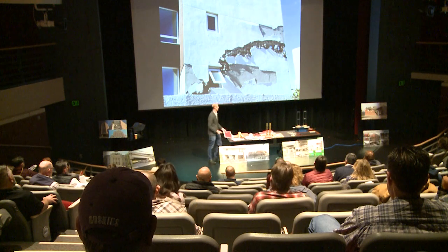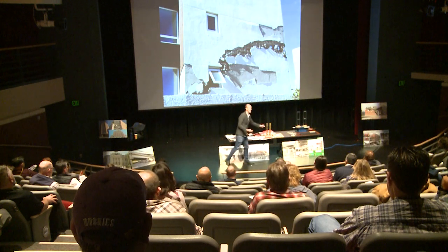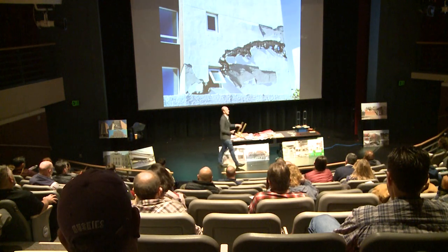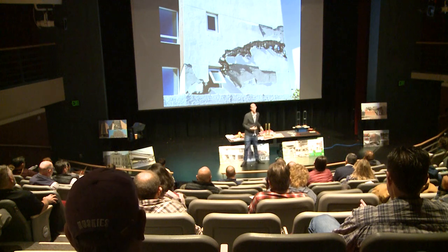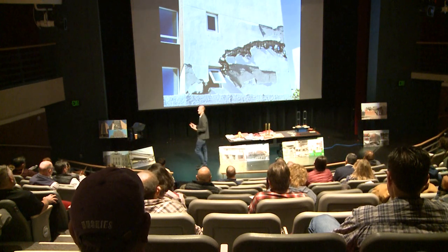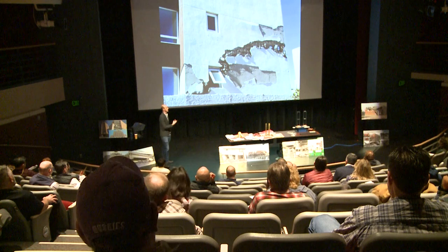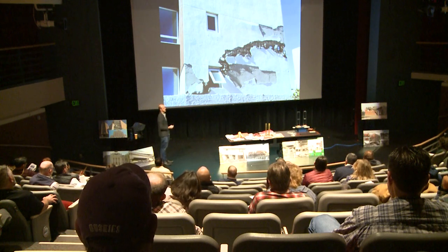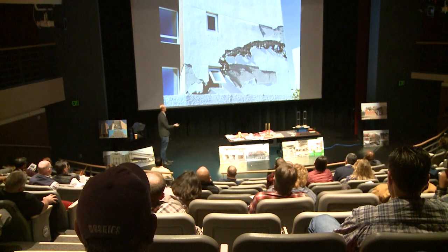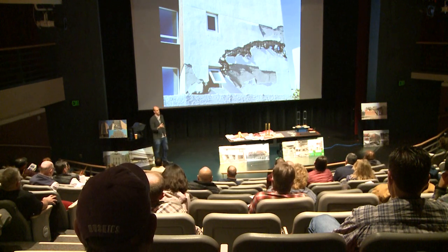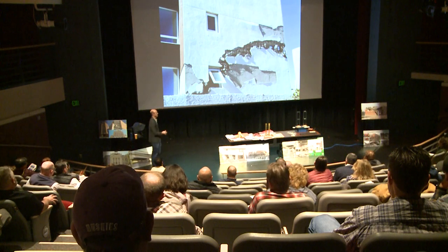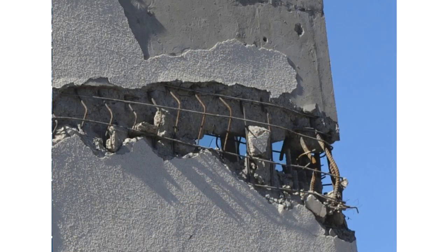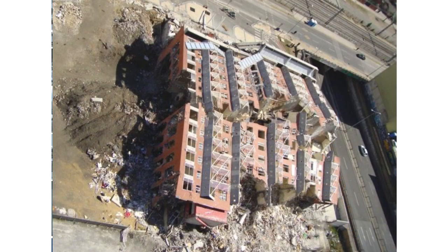And so we detail a reinforced concrete column. We detail this at the end of the wall, ideally. The term we use for that is boundary zone reinforcement. In this particular building, they didn't have that. And so when you look at reinforced concrete shear walls, just something to be aware of that ideally they would have a column embedded into the end of the wall. In this particular context, they eliminated that requirement from their otherwise US-based reinforced concrete design code. And that was the consequence of that.